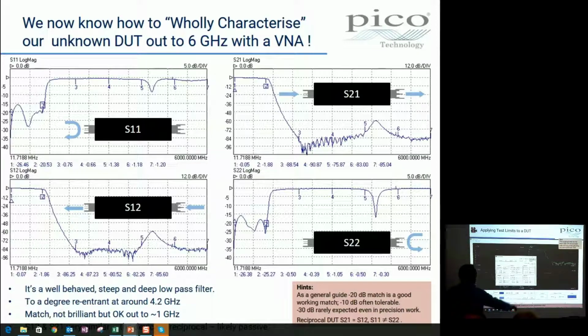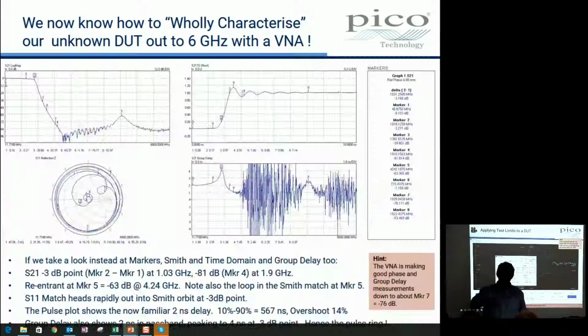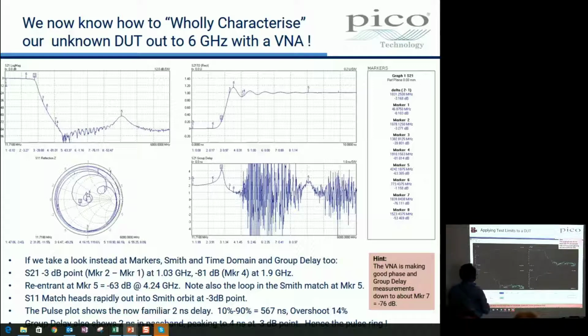All right, so when I use the limits button in the bottom right hand corner, I get limits for each of the display channels: 1, 2, 3 and 4. Paul, thank you, Paul. You challenged me earlier for not telling you which was which channel, and quite rightly too. And then each one has a start frequency, a stop frequency, an upper limit and a lower limit. And these are the limits that I've put in there. So you can get those displayed fairly quickly. The limits are different for each plot.